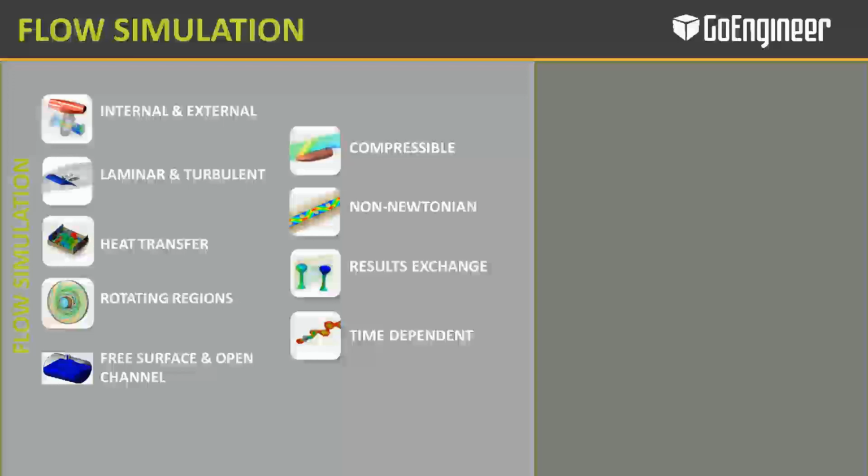Again, with a lot of components this small, producing heat, the strategic positioning of your fans, of your exits, of your heat sink is very critical to your design. And we're going to use Flow Simulation's capability to do full-blown CFD analysis to understand this behavior. So Flow Simulation can do both internal and external analysis. In our case, since the flow is inside the enclosure, we're going to do an internal analysis.